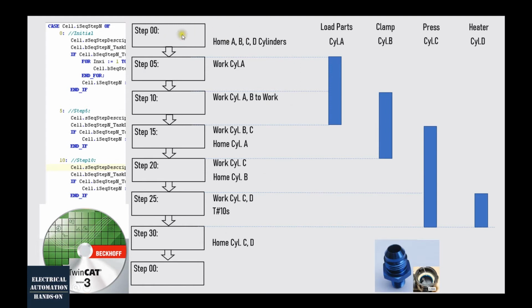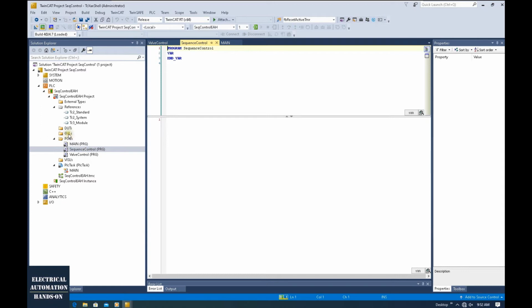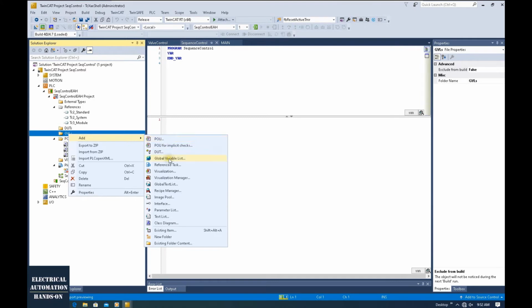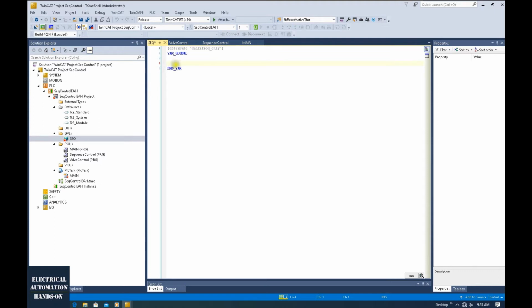The left area, we will use the sequence control to program this structure. And the valve control, we will program under the valve control program. In this video, we will mainly talk about the sequence control. Let's create some important tags from this GVL, the global variable list. For the sequence control, I will program SEQ. So all the important tags according to this sequence control structure, I will create or define under this SEQ sequence page. Let's create the tags within this area.